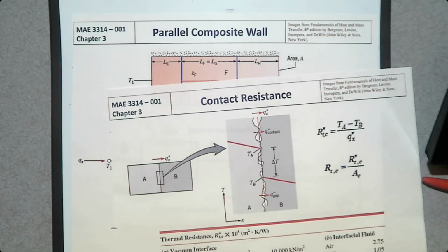Let's see what's going to happen if it is a transient heat transfer problem. Initially 20, 10 minutes later, 30, 20 minutes later, 40, 30 minutes later, 50, and an hour later, there's a fire in the house, right? So most engineering systems are steady state, and the way you study their heat transfer is most likely a thermal resistance network. That's important.